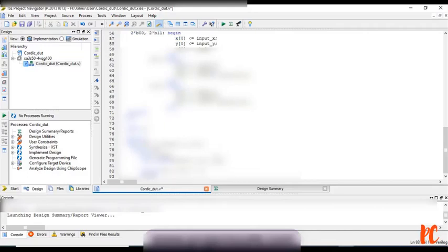Again assign y_SR is equals to y of i, again performing the shifting operator of Verilog, followed by finally assign z_sign, which I have already declared here, is equals to z of i followed by the last bit 31. Now let me write, this will determine the sign of the current rotation angle.